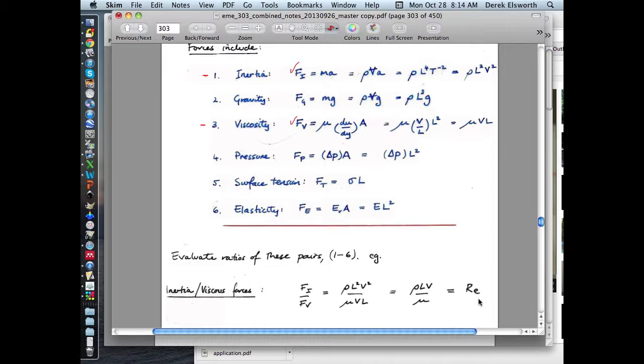So the Reynolds number is the ratio of the inertial forces to the viscous forces. In other words, inertial force is the force you have to apply to speed up flow within a flow, maybe around a dam or a weir. And the viscous force is acting against it. This one that we've used many times, right? This analog always acts against it. Friction acts against it. It's just really friction in the fluid, which is dissipating energy.